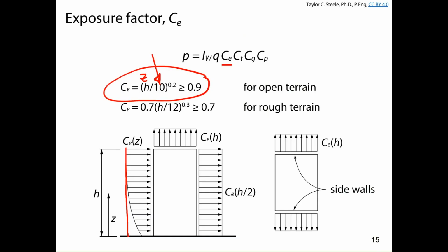Okay, so it's slightly conservative for us to just say, hey, I'm going to make this non-uniform pressure uniform, because that simplifies the structural analysis. I've got a uniform height. I know what my tributary heights are for the floors, and I can do my analysis this way. Okay, so this is a simplification, and it's conservative to do so. All right, so a conservative simplification for us to just take the uniform pressure with CE calculated using height H.